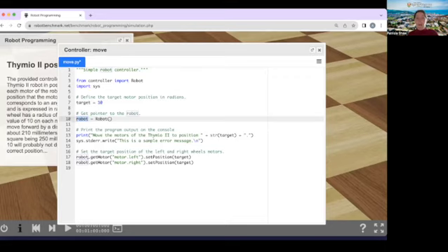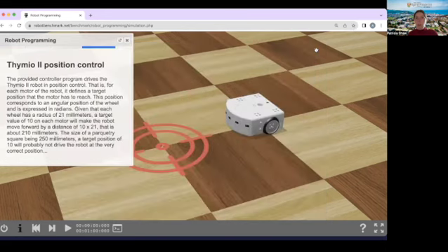And then down at the bottom here, it's getting the motors from that robot, and those are referred to as motor.left and motor.right, so we can get access to each motor individually. And then it's in position mode, so we can set the position for that motor to the target that we've defined up at the top. I'm going to save that program with just the 10 as a starting point in it.